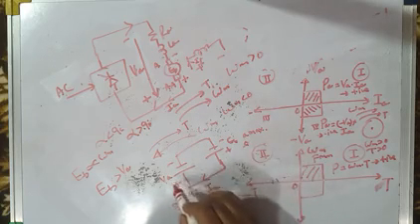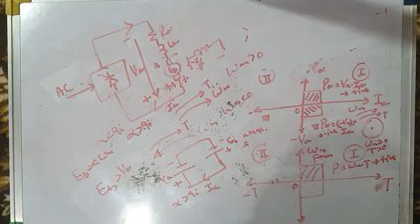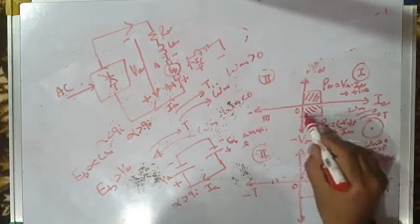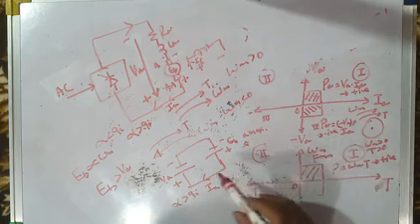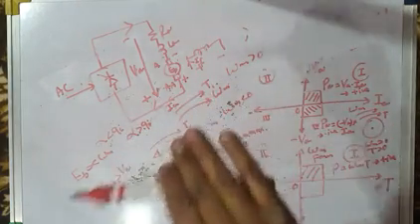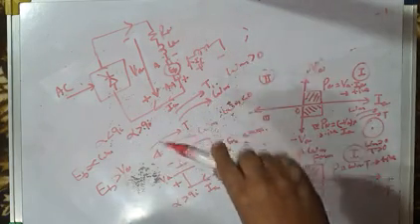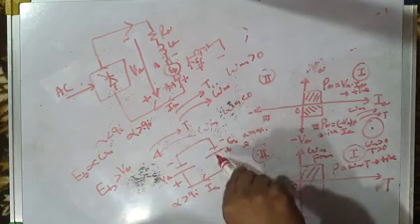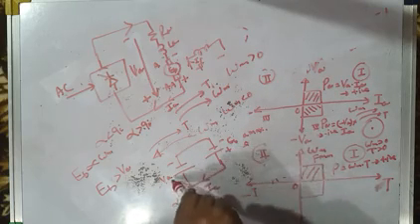It's flowing from EB to VA. It is a regeneration mode of operation. Our converter is operating in the fourth quadrant where power is negative. That means when the hoist comes down, it comes down very quickly. The motor machine reverses its speed and it overspeeds. EB becomes greater than VA.